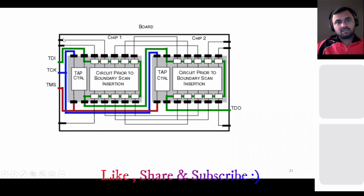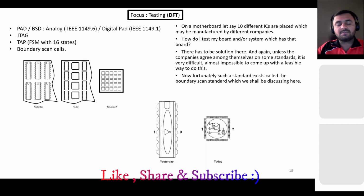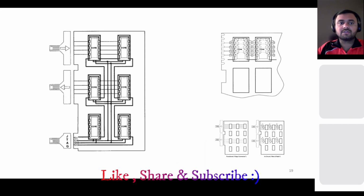So suppose in a board you have 2 chips. You can just put your input from this TDI, shift it through the boundary cells and shift out to the TDO. If you are shifting in and shifting out and you know the expected response, you can always compare it and see if there are any mismatches. Of course, for shifting you need the clock, so you need a test clock, and to select any particular mode you need TMS, test mode select. So this JTAG or boundary scan helps at your top level, and internal logic also you can test using that.